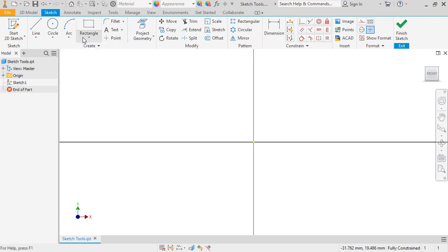The pin part, if you remember, had a hexagonal head and a non-threaded cylindrical post. To get started then, I'll sketch the pin head as the base and build the post later. You can draw just about any shape using the line tool, so I'll activate it from the ribbon and click anywhere on the screen to set the starting point.